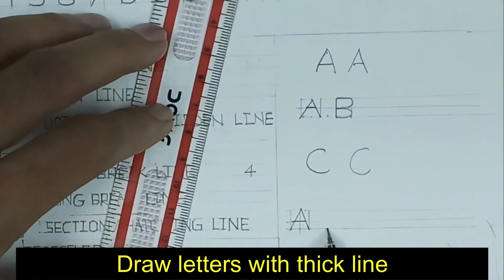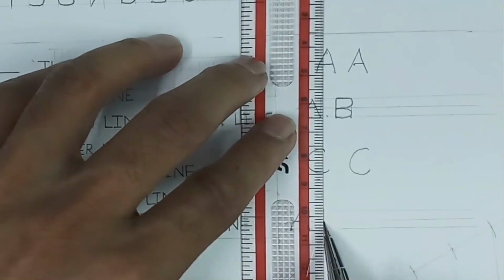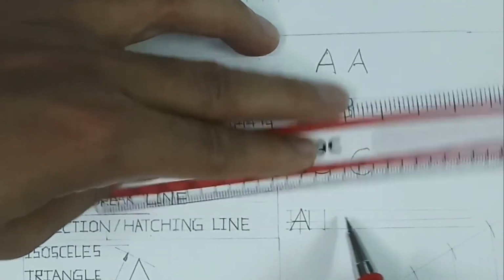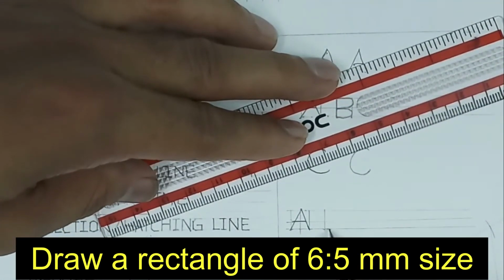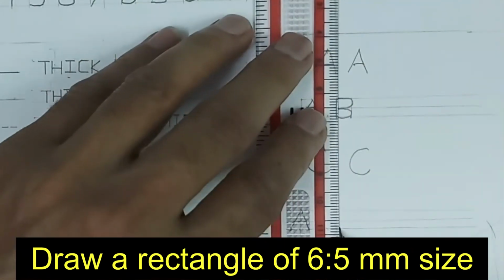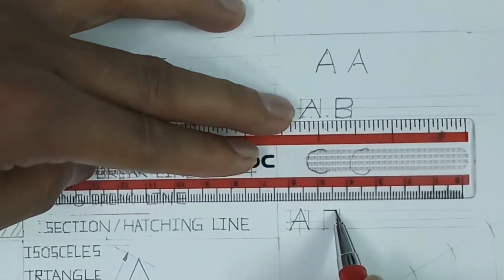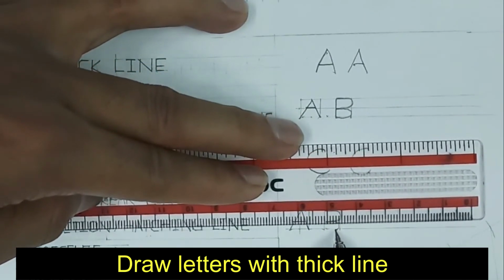Then keep a distance of approximately 5 to 6 millimeter between these two, and then we can go for the second letter. Let us say letter B. Letter B has a width equal to 5 millimeter. So for that I draw a rectangle of 6:5, where height is 6 and width is 5, and then within this we can draw letter B this way.